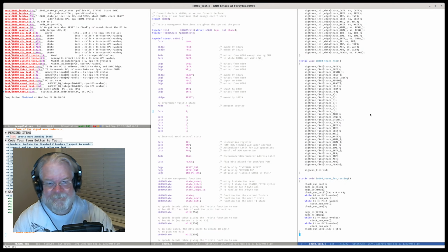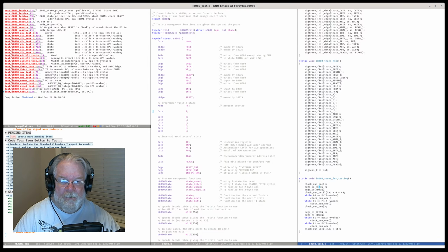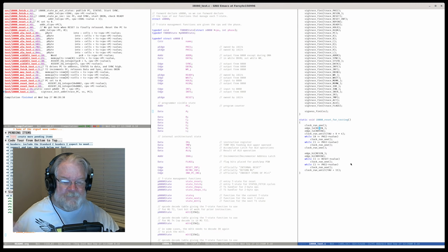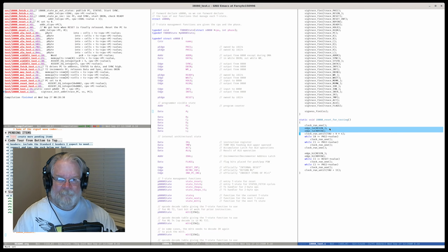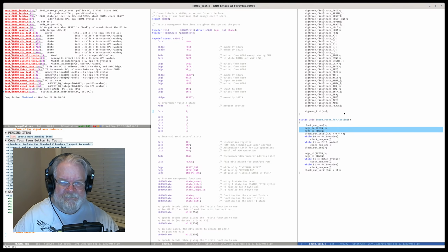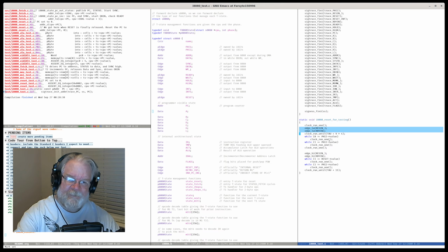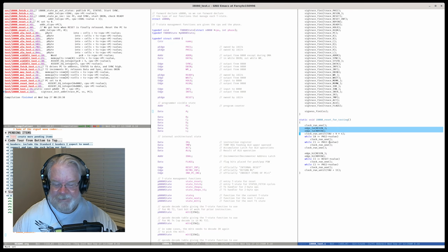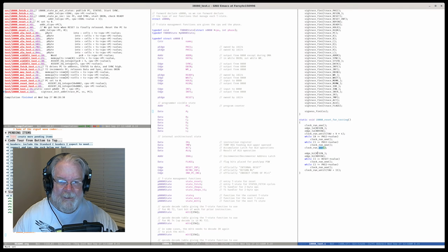And what we're doing there is an abbreviated test where we do a clock to make sure that we aren't in the same cycle that something else happened. We force the ready input and the reset inputs to be in the reset button is pressed state. And we run it until we see phi 2 going high and then low again, so we know we're near the end of a T state. One more clock. And then we set reset and ready to their inactive states. I'm actually not spending the extra time. Let's do one more.